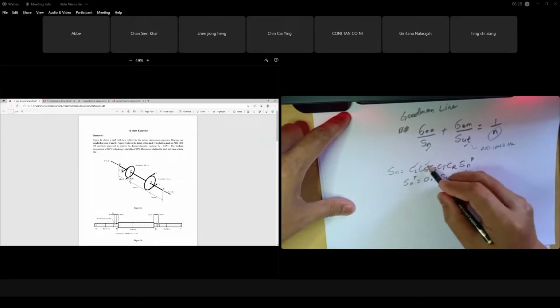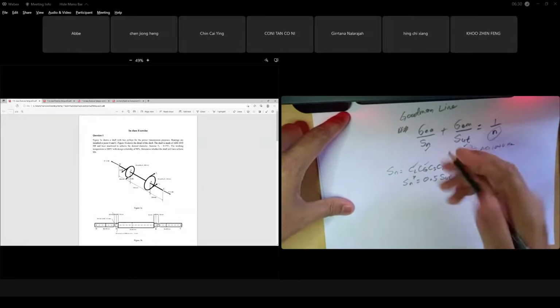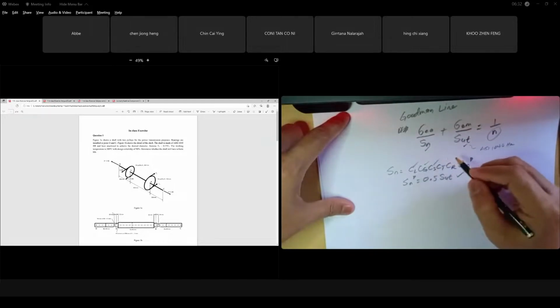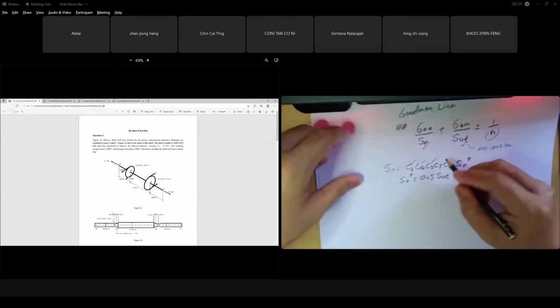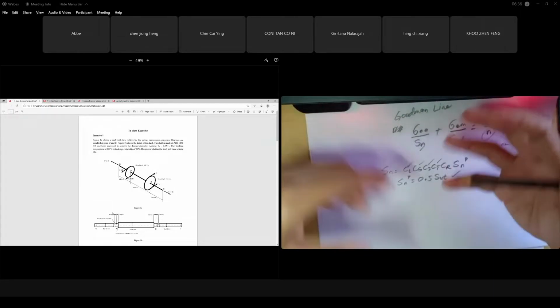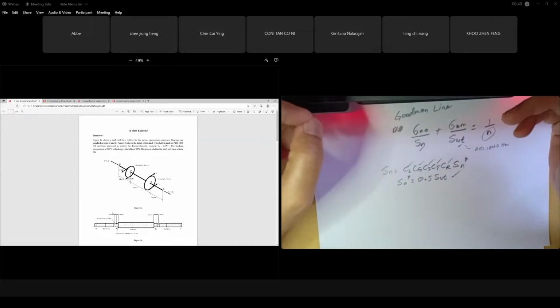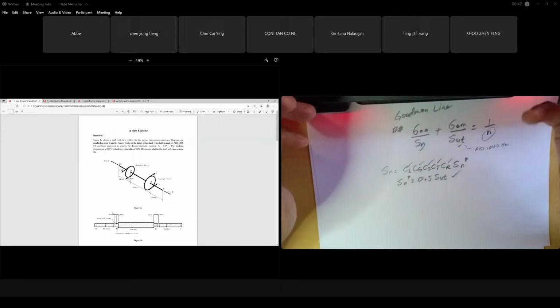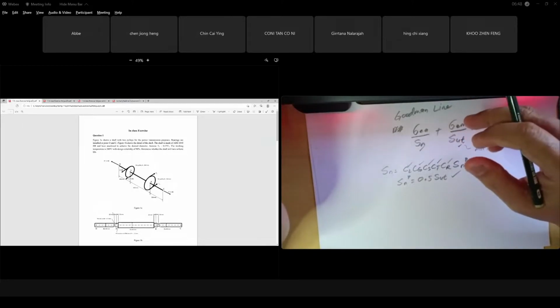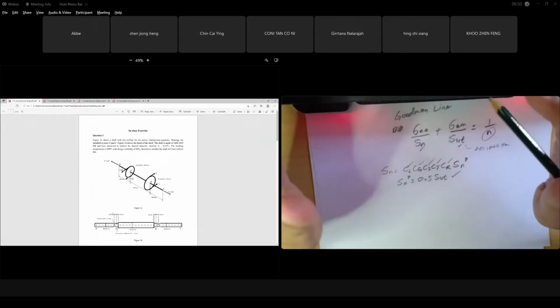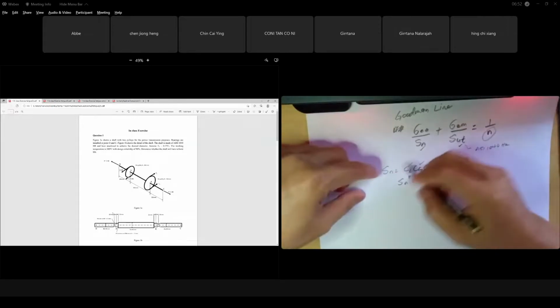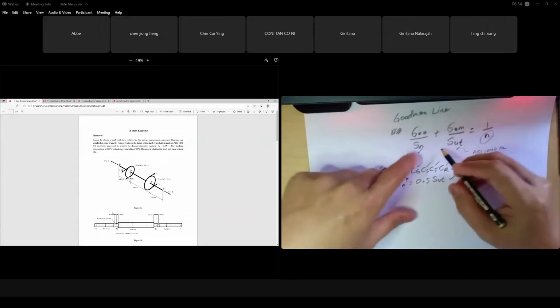Then the size factor, the gradient factor, is the size of your shaft at the point you analyze. Surface factor is the quality of the surface of your shaft. Temperature factor is the temperature during operation, and the reliability factor is given. At 99% reliability, you get 0.897 if I'm not mistaken. If not given, reliability is 1, because 50% reliability is 1. If not given, it means reliability is 50%. So you can directly get your S_n value, and so you have the denominator.